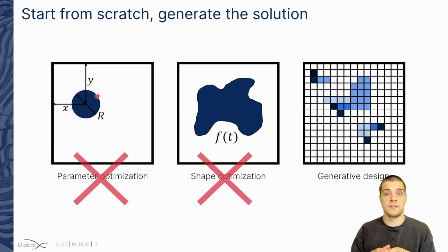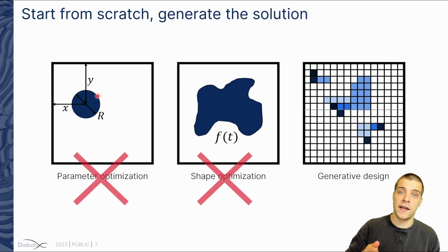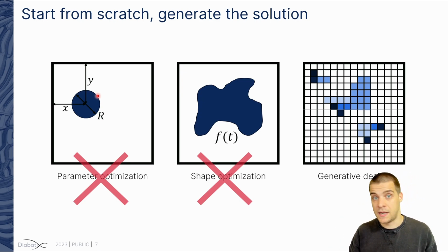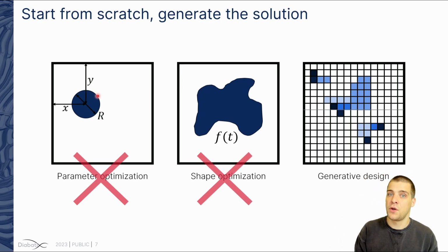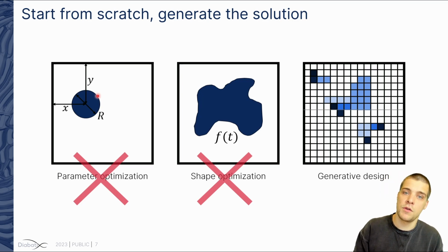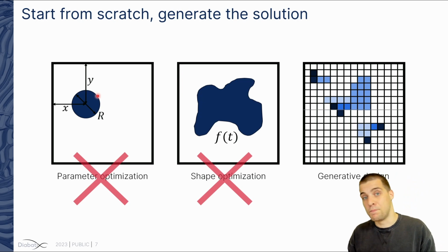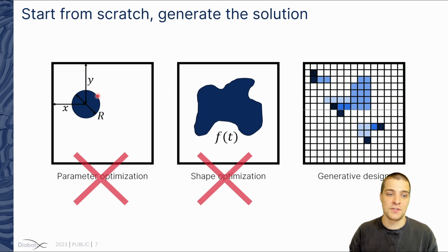We can parameterize the diameter of the pins, the height of the pins, the spacing between the different pins in both the X and the Y direction. And that's basically it. With parametric optimization, your amount of variables is very much limited, which makes it very accessible, but you're stuck with the design philosophy that you choose a priori. So you will never get something that's very organic, very interesting looking. But it's an easy way of optimizing.